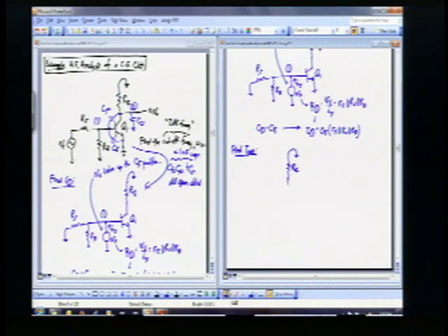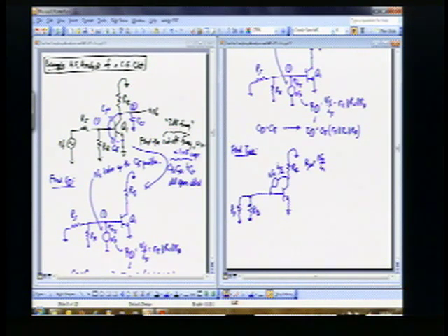So here's the RC. Here's my transistor going to ground. I still have my RB and my RS resistors. I open circuit all of the different capacitors, but I replace the capacitor that I'm interested in, which is the C mu, because I'm getting the time constant due to C mu, with a voltage source. So now I have to replace C mu with this. I have a Vx that I'm driving this, and I have to measure its Ix, and I have to calculate this R mu naught equal to Vx over Ix.